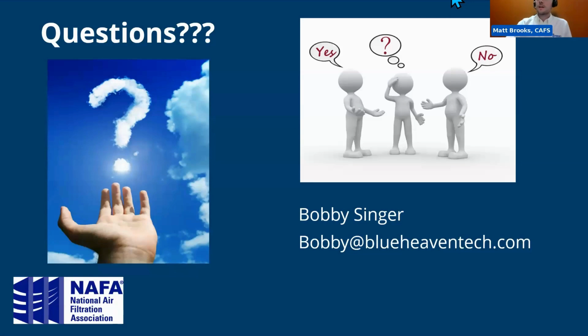There were a couple of questions comparing 52.2 testing to a HEPA test, and somebody asked if you could do a HEPA in a 52.2 test rig. Can you, without diving in, I know that's a whole other topic, kind of brush the top of that so people can understand that there are a lot of differences there that you know way better than I do? Yeah, you could test a HEPA filter in a 52.2 rig. I mean, odds are you're going to get a MERV 16 every single time.